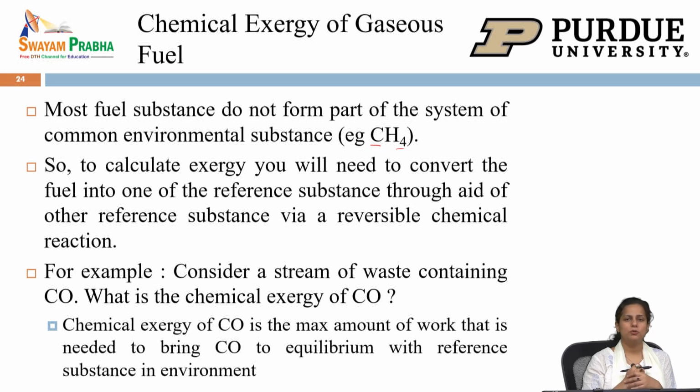Once you have that, you will write an equation that creates that substance from the reference substance. What we are considering is that for this particular fuel to come into thermal and chemical equilibrium with the environment in the dead state, it has to transform into one of the components of the reference state itself, or the dead state itself. So, since CO2 and H2O, water vapor, exist in the environment, if it has to be brought to the dead state, it will come into equilibrium with CO2 and H2O.